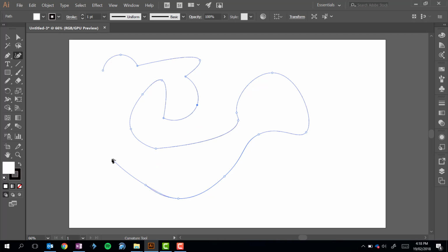When you're drawing using these tools and you want to create a closed shape, for example, it might be something that you want to have cut out with a laser, all you simply need to do is go up to where you started the line, and you'll notice this icon changes. If you left click there, it'll stop drawing and it'll create a complete shape. So now that's an unbroken line that if we went and sent this to the laser cutter with the right settings, it would cut that out and that would be the shape it would create.